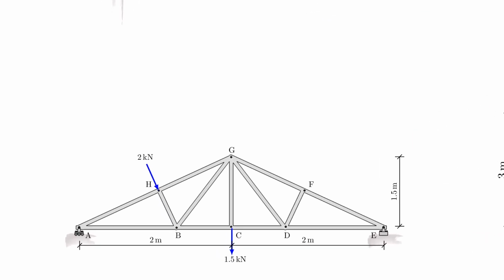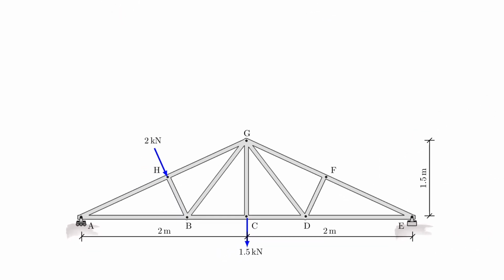Let's take the one here on the bottom. So now what do we have? Here we have two parallel forces and a random third one, but be careful now, there actually is a load now. So this cannot go to zero, right? If this would go to zero, this node would just not be able to resist the 2 kilonewton that's acting on the structure. So here, be careful. So that is not a zero force member.